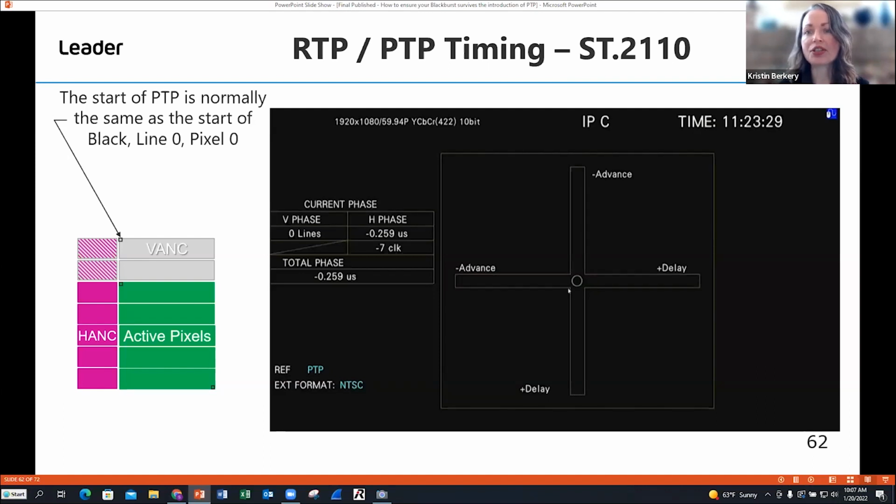It'll be interesting to describe how to monitor the relationship of the encapsulated sources from SDI to IP to the reference. Synchronization on 2110 is very important. It's important how to discover a source that's been encapsulated to 2110 but not locked to the same reference, or maybe not locked. The signal seems good, but it should create an AV timing delay. In this case, it's nice to find synchronization issues using the LV5600. How will PTP timestamp the video as well as audio stream?